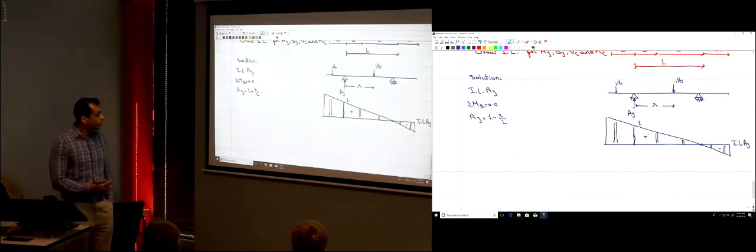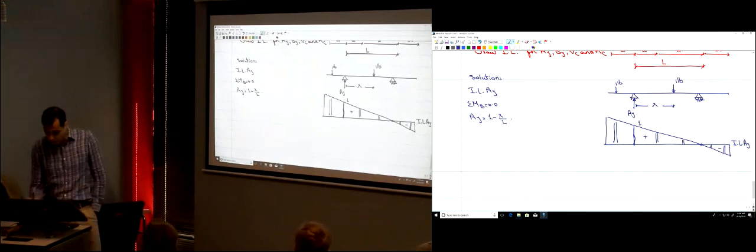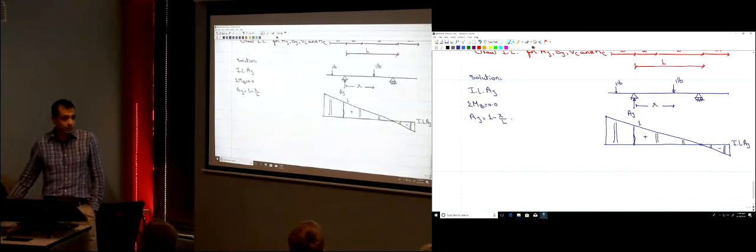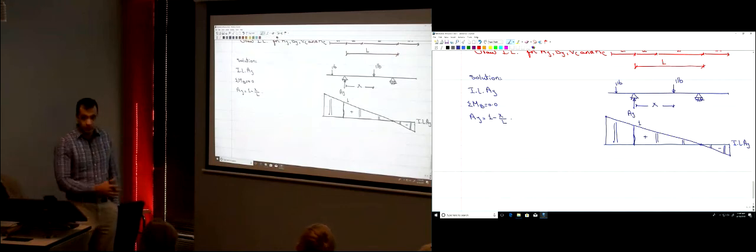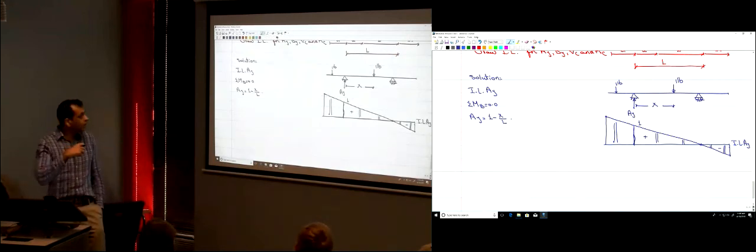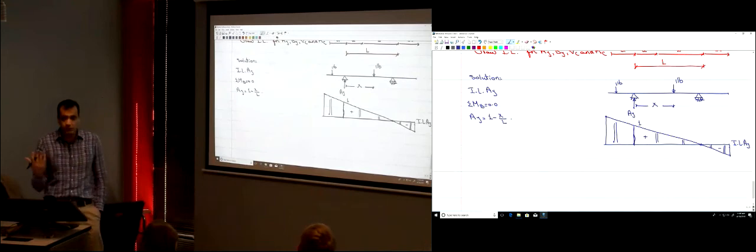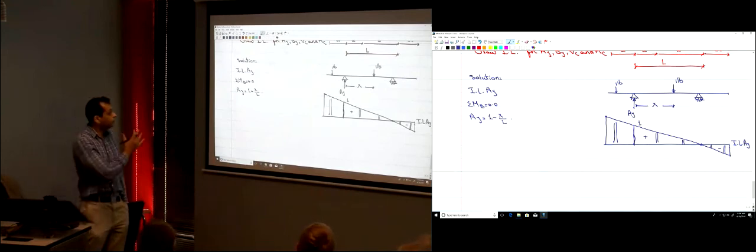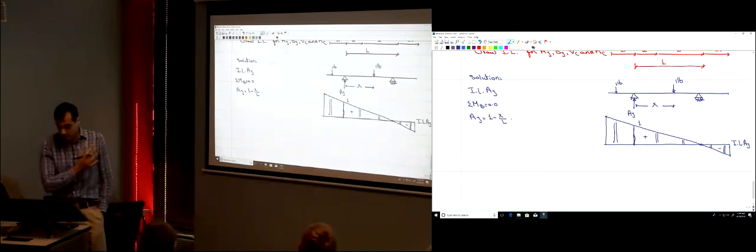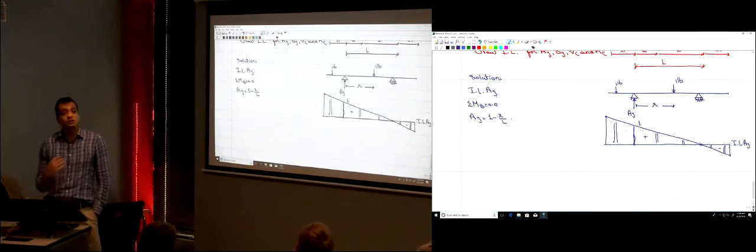Okay? So that means two important things here. How much is the magnitude over here at the end of the beam? It's not 1. 1 is at the support A. When the load is at point A, AY is equal to 1. All the unit load goes to the support A. But if it's over the overhanging part, AY is going to be larger than 1.